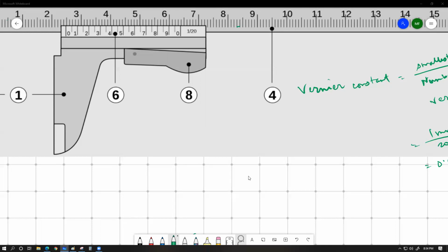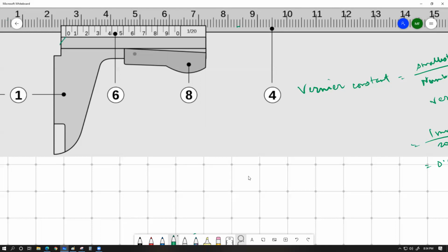So this actually means this is your 0 number line. This is your division number 1. This is division number 2, division number 3, division number 4, division number 5, division number 6. What I'm trying to say is that the printed marks over here actually represent a division number double that. For example, if you're trying to take a reading of, let's say, this line, the label is at 7.5 on the scale, but in terms of division, that's going to be 7.5 multiplied by 2 equals 15 divisions. This should be read as the 15th division.